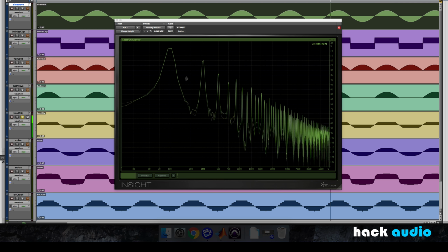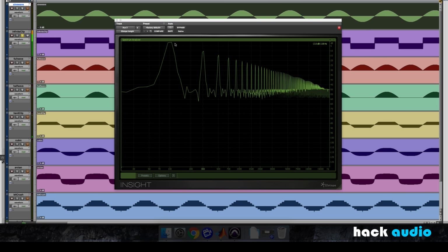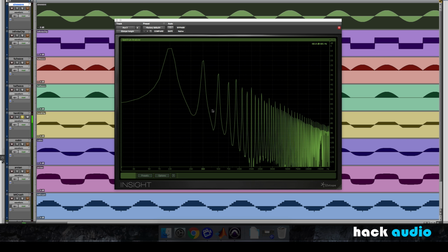There is a difference here if you look at the waveform of our hard clipper compared to infinite clipping. In this case, the amplitude of these harmonics rolls off at a quicker rate than it does for infinite clipping. Here, with our square wave type signal, the amplitude of these harmonics stays higher. But when we go to hard clipping, it's not going to sound as harsh. The amplitude of these harmonics falls off at a quicker pace. We can compare this function for hard clipping to soft clipping.